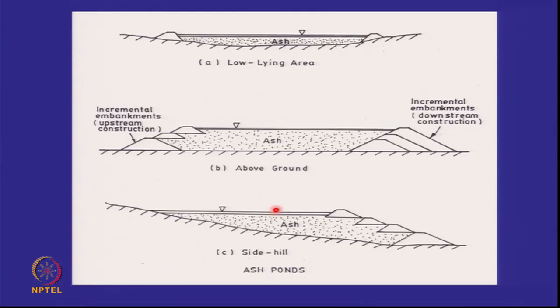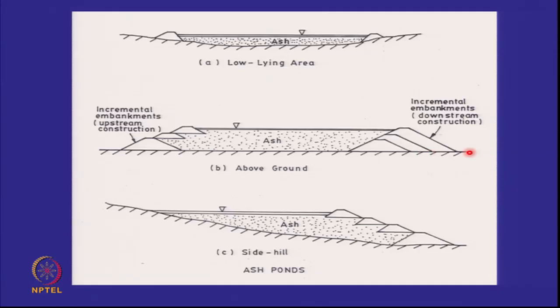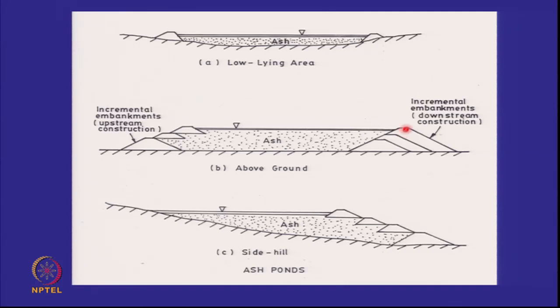The other important thing about these slurry ponds is they have to go to their final height. The final height of a slurry pond above ground, let's first look at flat ground, may be 20-25 meters. There are ponds of mine tailings which are 40 meters high, and I told you the Kudurmukh iron ore tailings pond is 100 meters high, but it's only a cross valley impoundment. So only one embankment is made and it is 100 meters high. Typically on flat ground this will be 20-25 meters high.